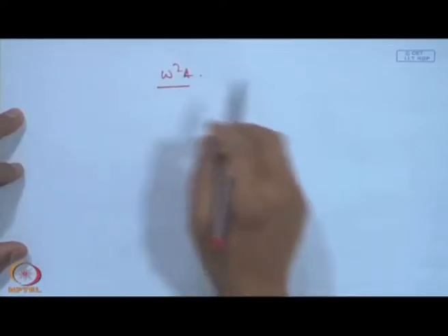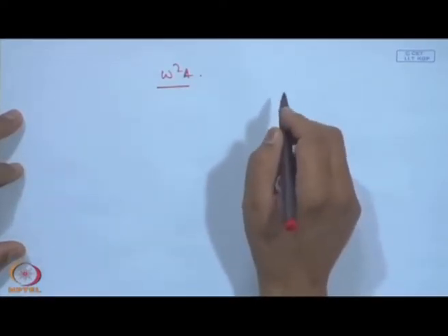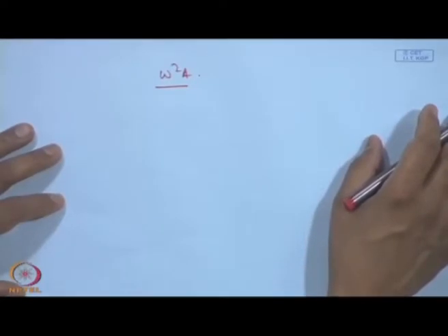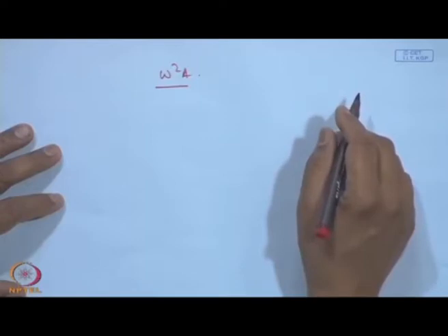Of course, another one is the LVDT. And then one thing you would notice is that be it an LVDT or a dial gauge or for that matter an accelerometer, they have to be always in contact with the surface at which we are measuring the vibration. But there are instances where we cannot touch this surface.